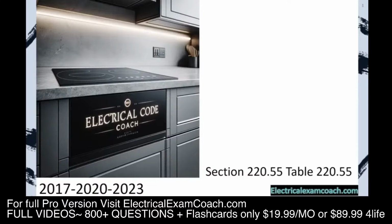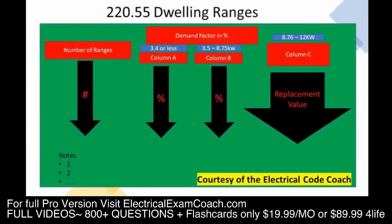Let's get to it. When we get to table 220.55, we're going to read the black bold heading at the top of the table to make sure that we're in the right table. Then, starting on the left-hand side, we're going to find our number of ranges: 1, 2, 3, 4, 5, and so on and so forth.